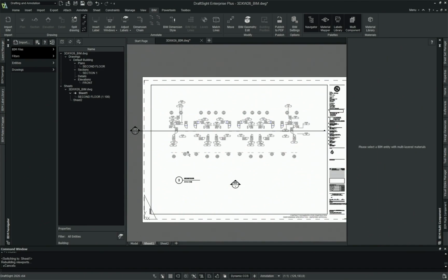So you can create door schedules in this example here. I could show you if you'd like. You create the filter to say, I want my second floor doors. And once you have that assigned, you can create a table automatically and lay out your doors with whatever information you want in a table and then throw it in your drawing. And so then you'll have an automatically generated door schedule.